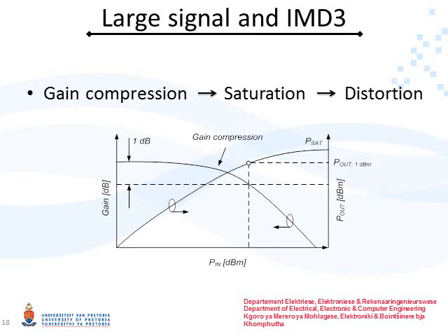In terms of the large signal analysis, all power amplifiers suffer from the nonlinear effect of saturation, where the gain begins to decrease with increasing input power, known as gain compression, as shown in this figure. One cause of this phenomenon is device heating caused from the power dissipation of transistors, resulting in self-heating. This is most noticeable at high current densities.